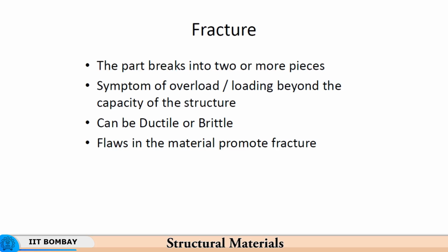Again, the idea here is that even if there is some overload, there should be no failure of the lift. So, here failure will refer to the lift being unable to lift the load up, and so it does not refer to any fracture as such, but its inability to lift the load or go up and down. So, fracture is a much more serious situation compared to just failure.